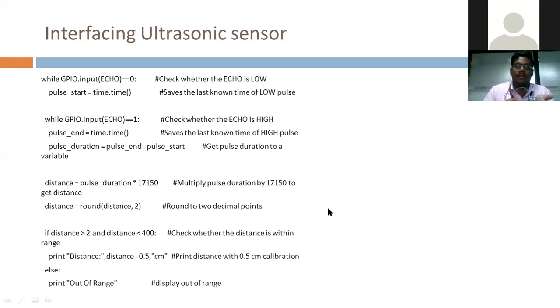We just start from this notch. Whenever the camera is connected, you start counting from that point: 1, 2, 3, 4. So I'm taking 5 volt, ground, GPIO 23 and GPIO 24, which are the 8th pin and 10th pin.